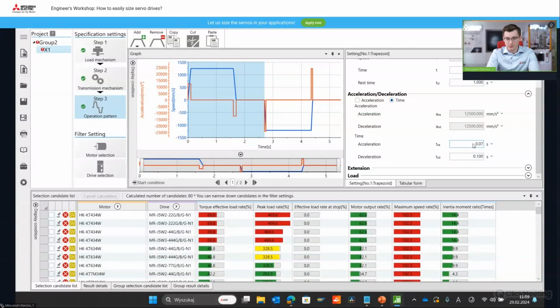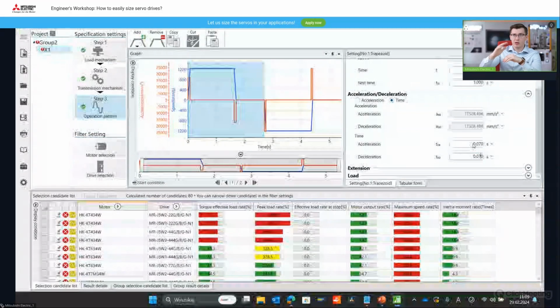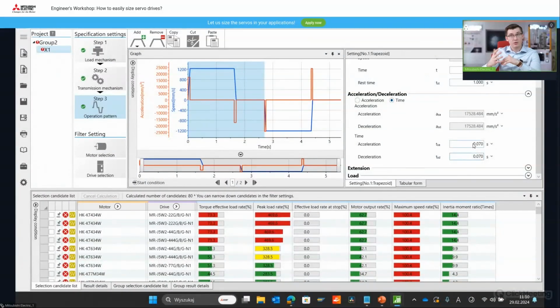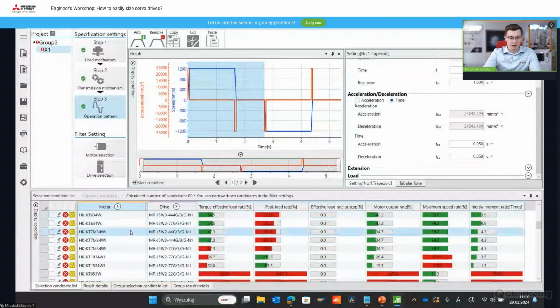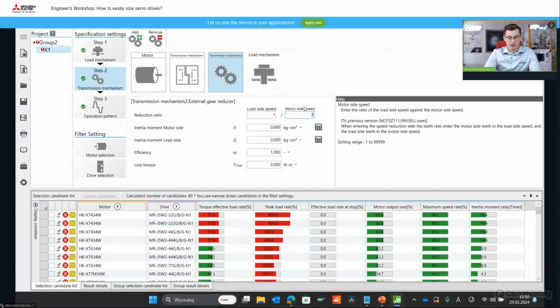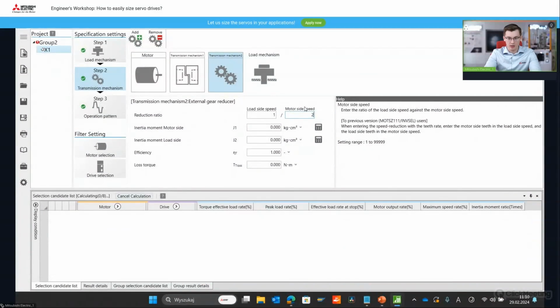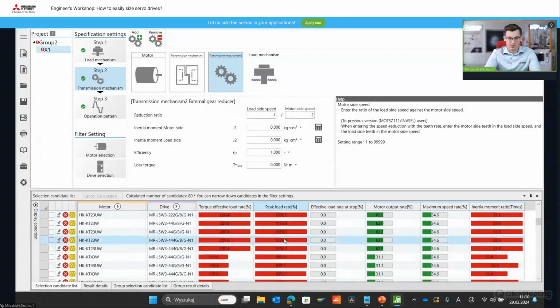Yes. So for example, you have to check. You have to find the exact acceleration you want to have at the application, because let's say the smaller the acceleration, the smaller will be the maximum speed, and then you can sometimes use the gearbox to the system. But okay, so let's go back with 0.02 because of the speed, and if we are not able to do anything about that, let's say we will change to 2. And now the maximum speed is okay.